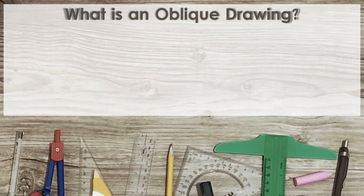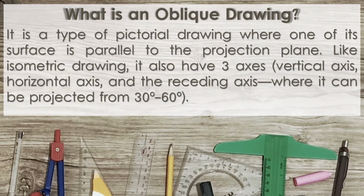What is an oblique drawing? It is a type of pictorial drawing where one of its surface is parallel to the projection plane. Like isometric drawing, it also has three axes: vertical axis, horizontal axis, and the receding axis, where it can be projected from 30 degrees to 60 degrees.